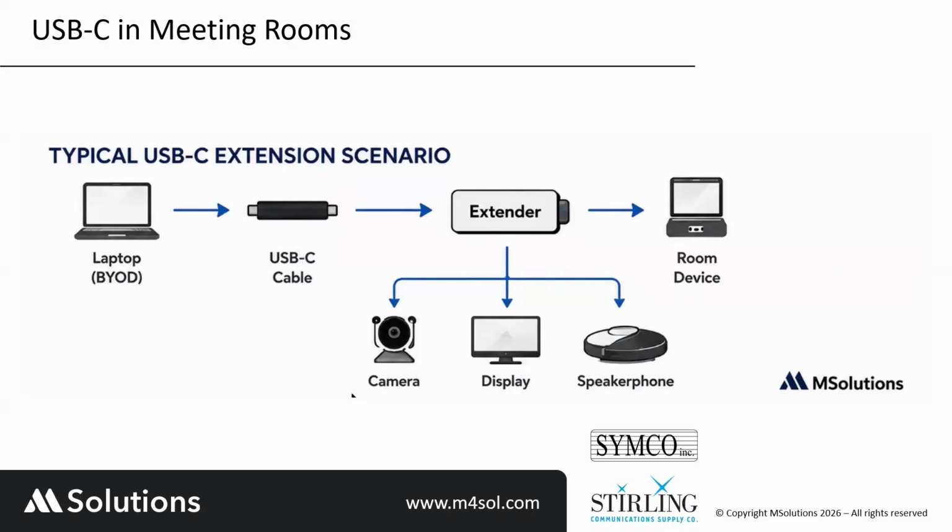And I'm saying what we are aiming to because, again, and I will repeat it many times because I'm getting the complaints of this is not working and that is not working. One USB-C connection can replace multiple independent cables, simplifying both the installation and the user experience. But at the same time, we must, and this is mandatory, we must verify that not just the laptop can transmit a video through USB-C. We need to verify that the cables that we're using are capable of that.